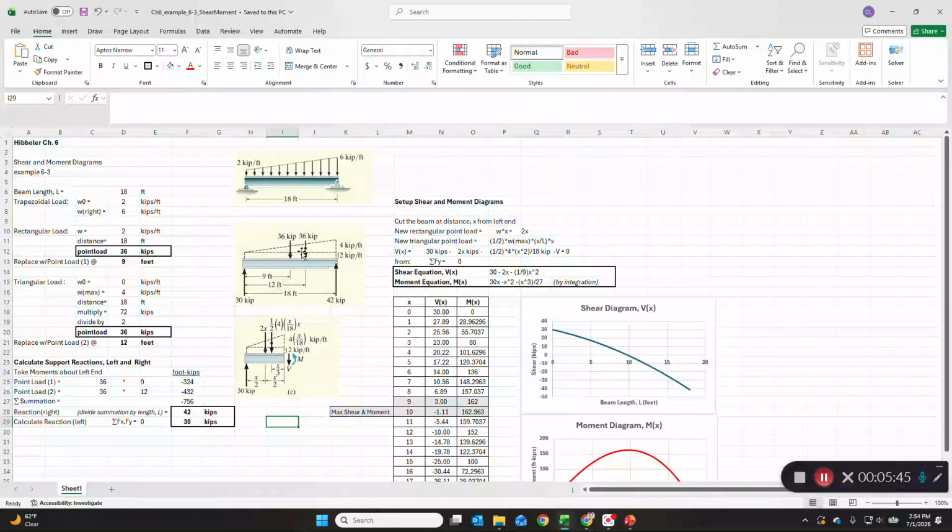So then you have 36 kips at 2/3 of the distance, excuse me, of 18 feet here with this other load on the right. So I'm only talking about the point loads now. So 36 kips at the center is going to be 18 and 18 at the supports, and that balances to 36. But you have another 36, 2/3. So 2/3 of the 36 would be at the end of the beam that's closer to the load.